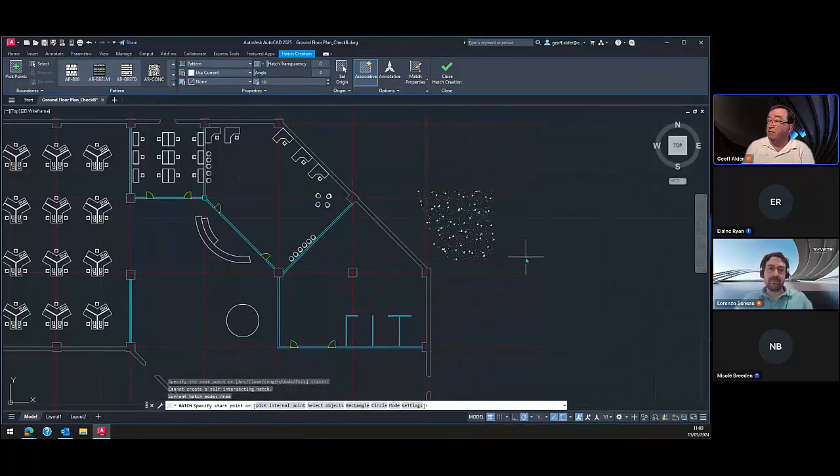So instead of creating a polyline and then using a boundary projection to do this, I can actually place that on there. I find this quite useful. If I want to put a hatch pattern across several components, I can just tap round the component to highlight where the hatch is going to be, because if I need to do it as a select internal point, I need to select islands or decrease islands and stuff like this. So I quite liked that.